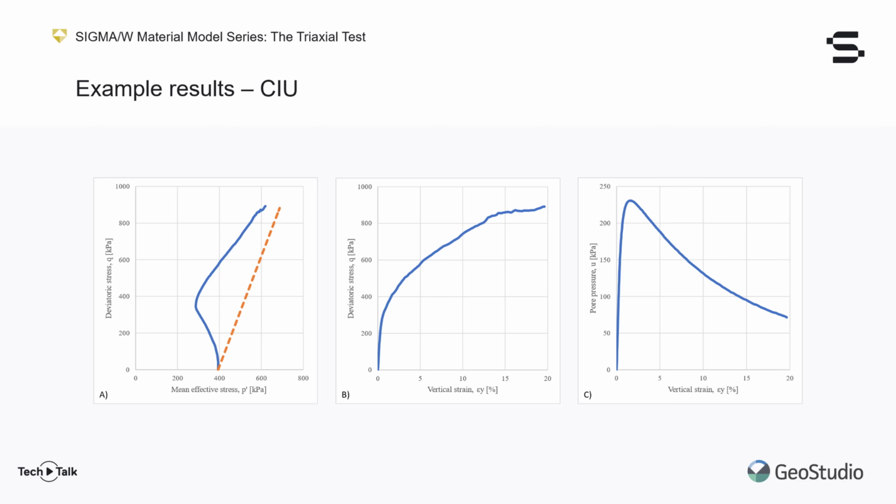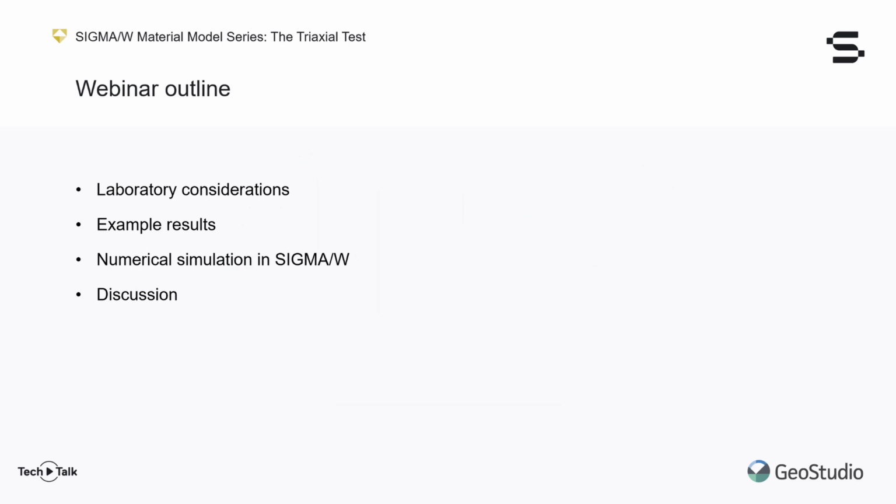As I have shown earlier, superposing the total stress path with the effective stress path allows us to visualize the excess pore water pressure that generates during the test. Notice how the effective stress path remains to the left of the total stress path for the entire test. This indicates positive excess pore water pressure. A denser soil sample could very well generate negative pore water pressure because of its tendency toward dilation. This would force the effective stress path to cross to the right side of the total stress path.